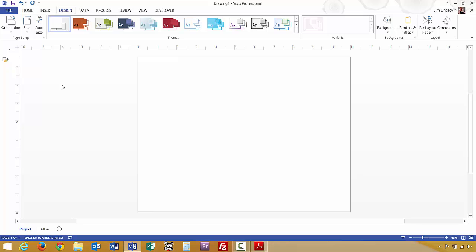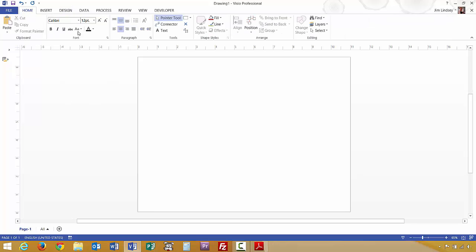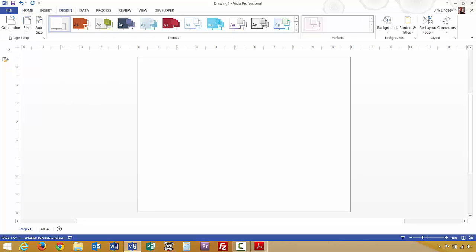Where that's helpful is, let's say you have a really big network drawing that you're not going to print, but you're going to output as like a web document. At that point, if you're not going to physically put it on paper, it wouldn't matter one way or the other. So auto size at that point doesn't become something cumbersome. But for you guys, you don't need it. So again, from Home, go to the Design tab of the ribbon, make that orientation landscape, and then where it says auto size, click on that blue thing to turn that off. So there you go.